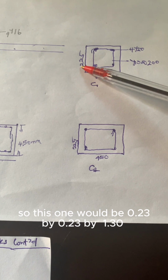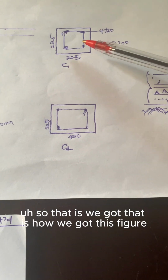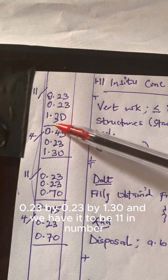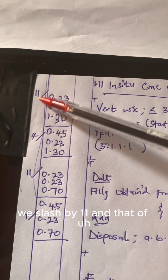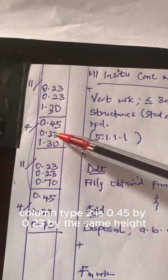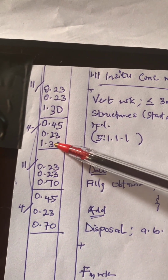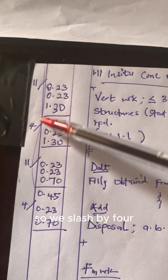So this one will be 0.23 by 0.23 by 1.30. So that is how we got this figure: 0.23 by 0.23 by 1.30, and we have it to be 11 in number. We slash by 11, and that of column type 2 is 0.45 by 0.23 by the same height, but in this case we have 4 number, so we slash by 4.